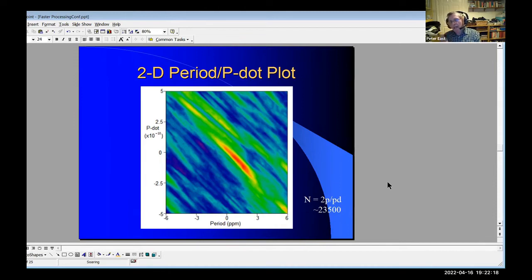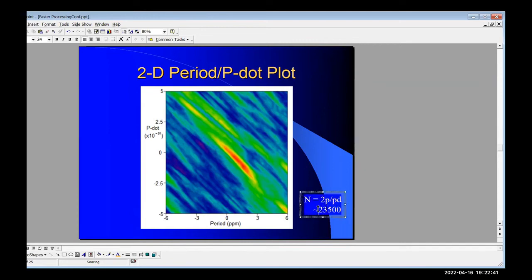And because it was at night, I did try to do some measurements during the day back in July, and that wasn't fun at all. I was just dashed with RFI. Well, I do know that B0329, or I recall that its polarization does rotate over time. So your best approach is to use a dual polarization reception setup, and then do post detection combining of some sort, and effectively you get scintillation and polarization showing up.